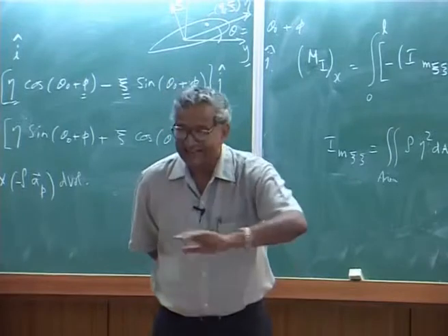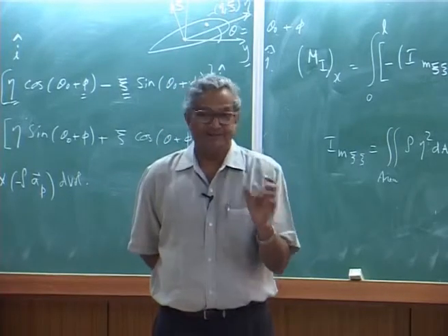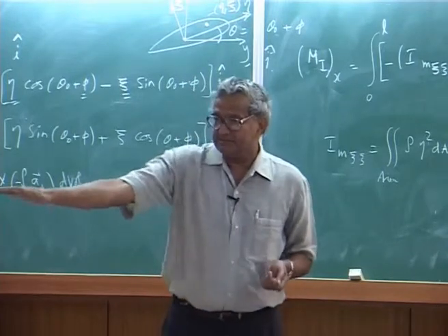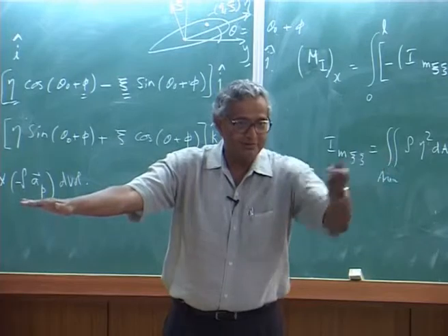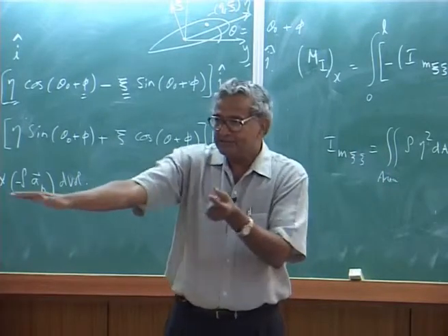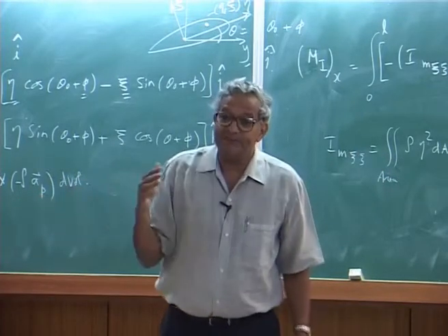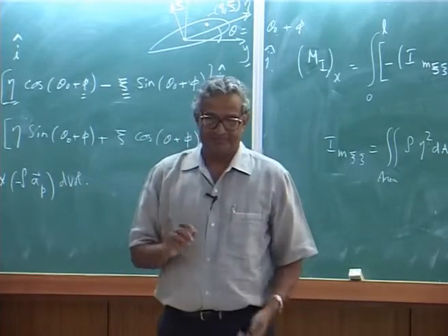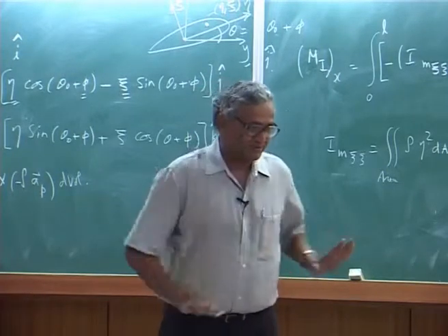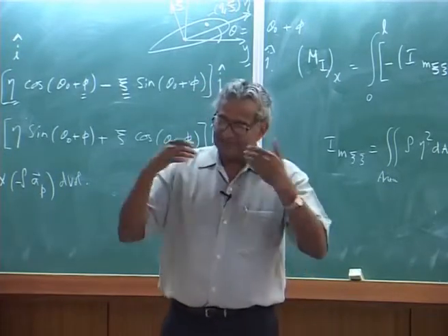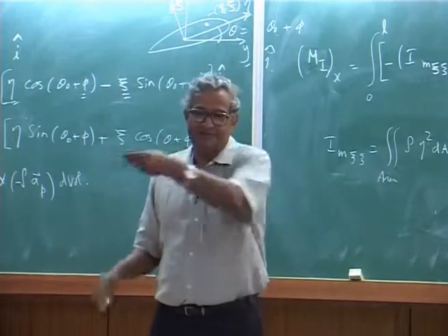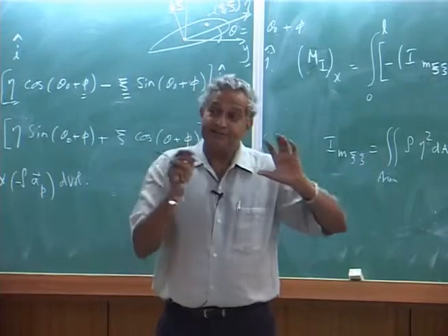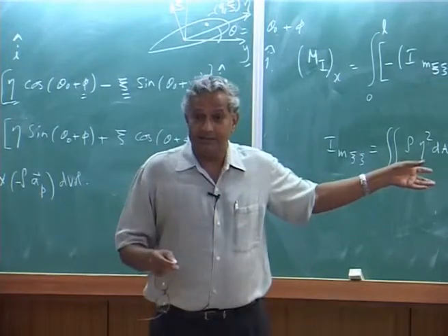When you talk about lead lag, I never expressed any aerodynamic term for lead lag motion also. You are having the blade moving like this, the flow is coming, that means it is a pulsating flow. You want the drag force in a pulsating flow. We do not have expressions for those things. Later we will make a lot of approximation, and that is why we will say, okay, this is the aerodynamic load. That is why I did not put any aerodynamic expression when I derived my lead lag motion.